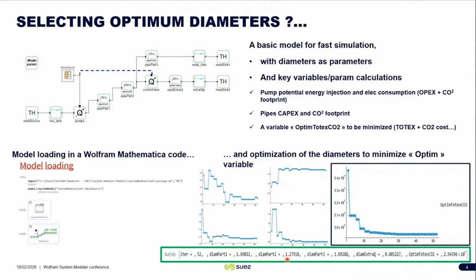The resulting optimal design is kind of obvious and at the same time interesting. The long microtunneling pipeline in this example converges to a small diameter because of the construction costs. And on the other sections, the lower differential cost converges to a larger diameter to reduce energy consumption. So it finds the balance in an expected way on this example.